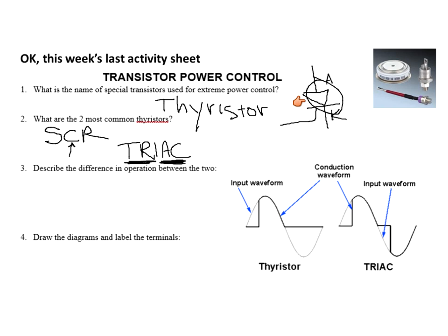This one, when you look at the schematic diagram, it actually has two diodes in it, one facing up and one facing down. And then it has the two terminals where all the current flows, and it has a gate on it which does the controlling. This terminal up here is called mounting terminal number 2, and this one's called mounting terminal number 1. And this is called the gate. The gate is how you control it. So this will conduct forward and reverse currents through it because you have two diodes back to back. And that's why it can conduct AC.